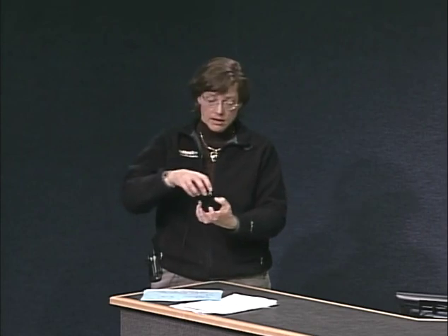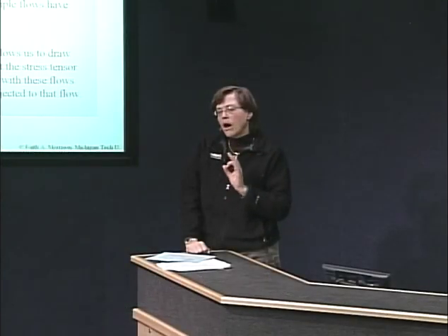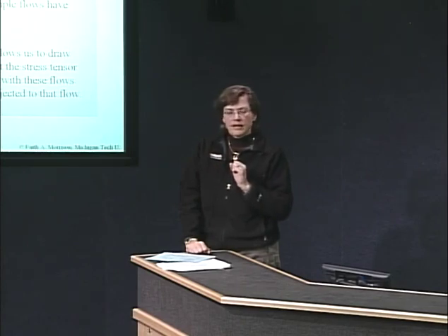So why not just follow material science and stick them in an Instron tensile tester and move the plates across following some ASTM standard? I'm going to discuss that now. Okay, why not a simple test like that? Seems like everybody does that already. It's very well accepted. Remember, our goal is to relate our measurements to the constitutive equation. The constitutive equation is an equation that relates stress and deformation.